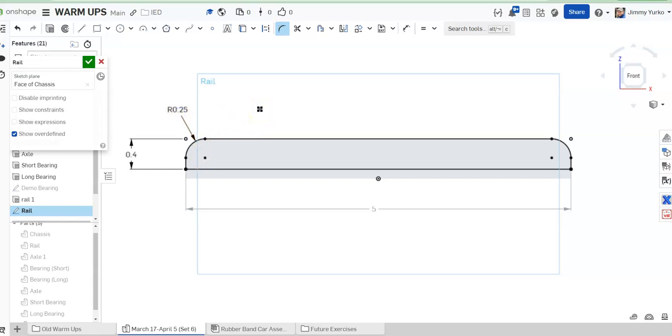And we're going to go ahead and add holes to the design. Circle is what we'll draw. C is the shortcut for circle. I'm going to draw mine right on these center points that appeared for the fillet. That will save you some steps.